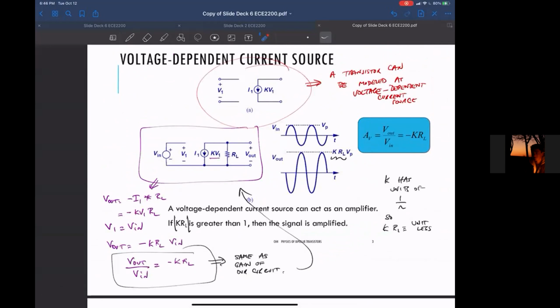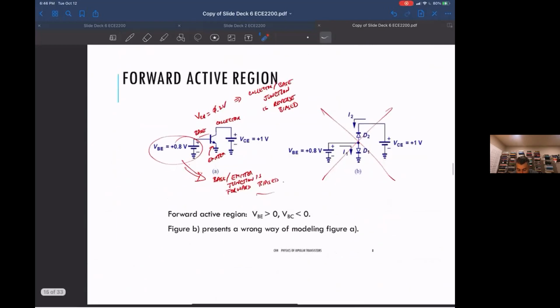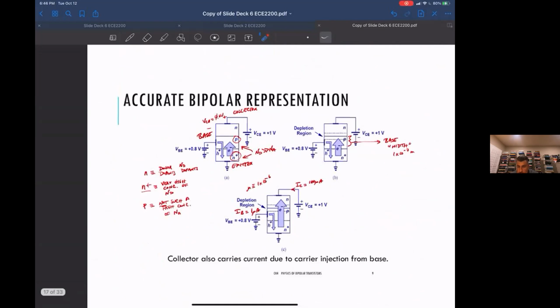I wanted to say real quick before we get to that. You said the two main points were that the emitter is doped much higher than the base. And then what was the other main point? Is that the physical width of the base has to be so short that these electrons just go straight through the base and end up in the collector?